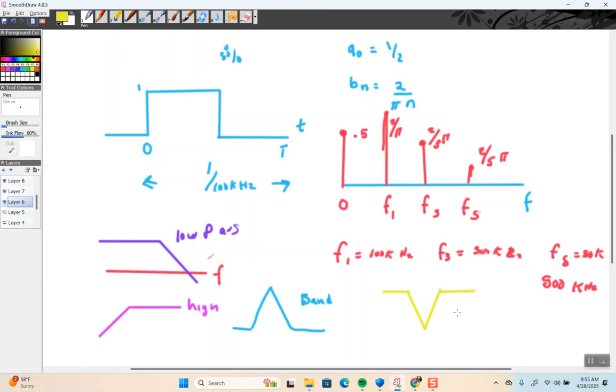Think about it. The amplitude is multiplied by this number up to a point, and then that number decreases with frequency: low pass. Here, it's attenuating low frequencies, because remember, these are all sine waves multiplied by the attenuation constant, and that's our output. Here, it's kind of like 0, and then it passes one frequency, and here it blocks one.